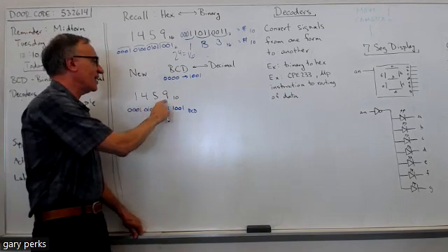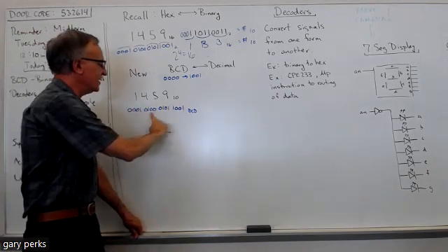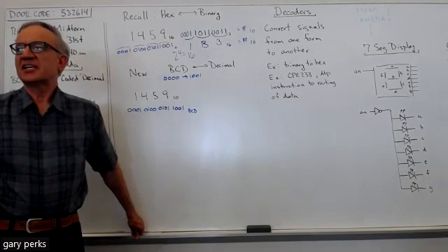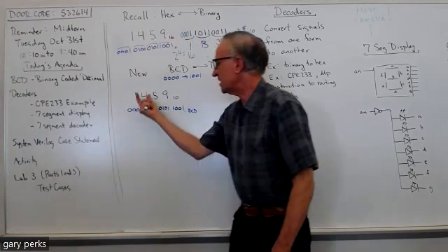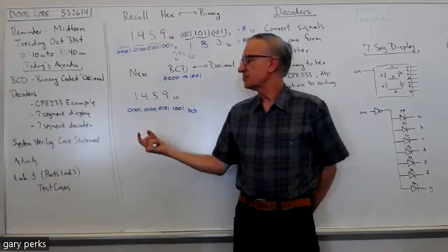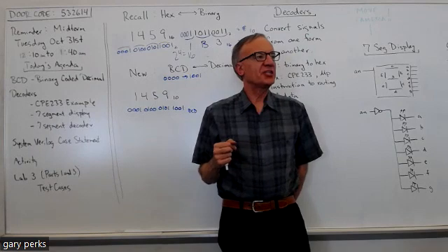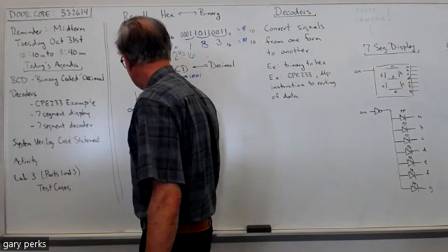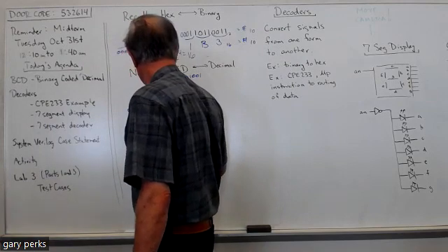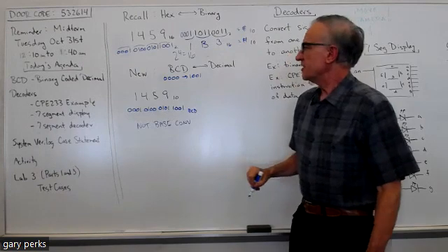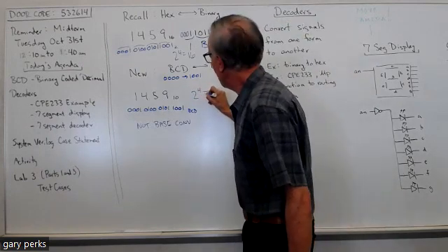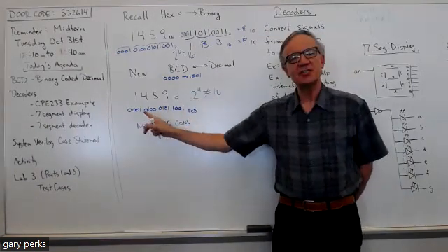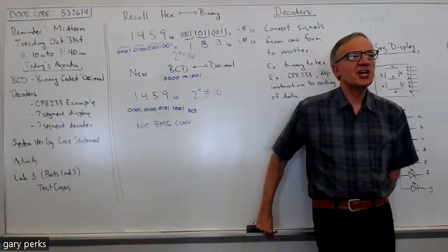We're not saying that 1459 base 10 is equal to this in like a binary sense. We're just representing each base 10 digit as a 4-bit binary group. Okay, but it's not base converted. So, write in your notes, not base converted. Right, because 2 to the 4 does not equal 10. So when you write a base 10 number using the 4-bit grouping, you're not doing base conversion.